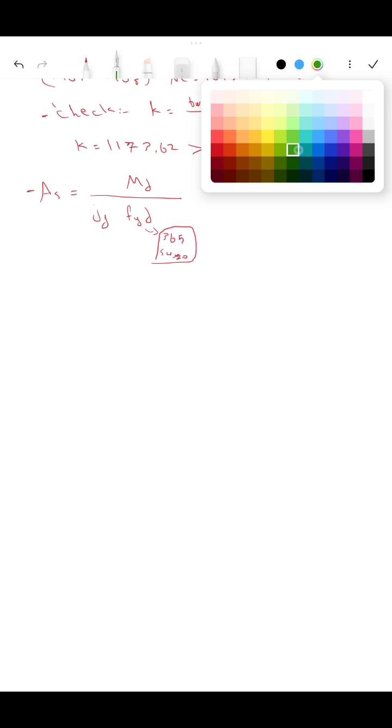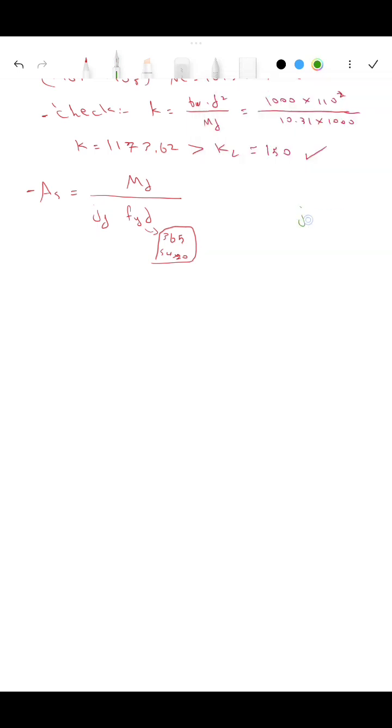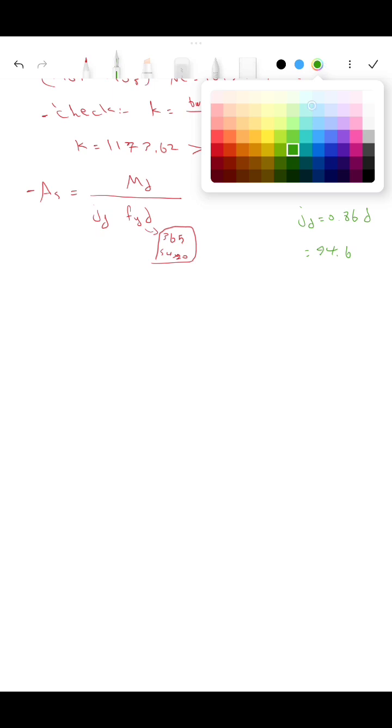let's calculate JD on the side. JD in general equals 0.86 times D. So 0.86 times 110, and it equals 94.6. Okay, after that,